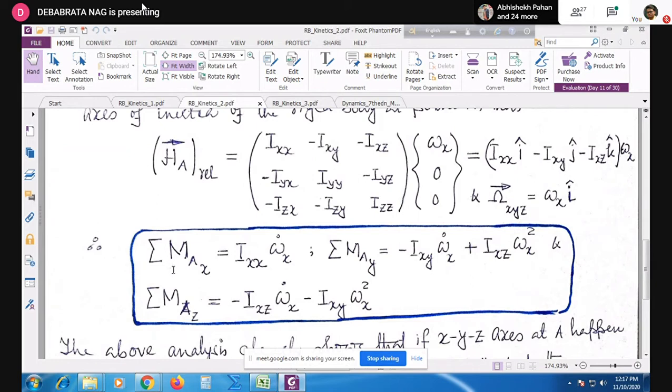Please remember, this is a very important point, it needs to be applied in the correct free body diagram of the rigid body. So you need to first draw a correct free body diagram disclosing all external forces and moments which may be acting on the body, and on that body you need to write your Newton's equation or your Euler's equation as per your requirements. So please note, along with this we have Newton's equation, but before going into the discussions further, we need to understand this equation.